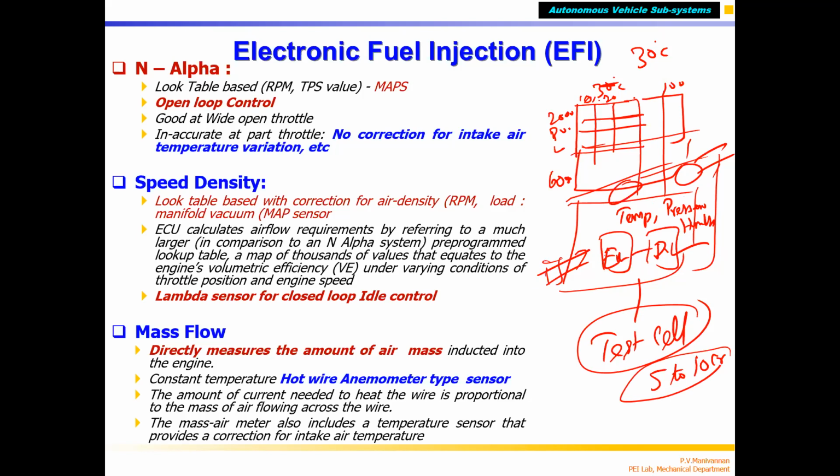Apart from that, you have the dynamometer with a lot of sensors, correct? Fuel measuring sensors, air temperature sensors, throttle position, all those things, and an exhaust gas analyzer. Exhaust gas analyzer, which measures HC, CO, NOx, can measure from 1 to 4000 ppm of NOx, similarly 0 ppm to some 300 ppm of HC, and CO, carbon monoxide, from 0% to some 10%.